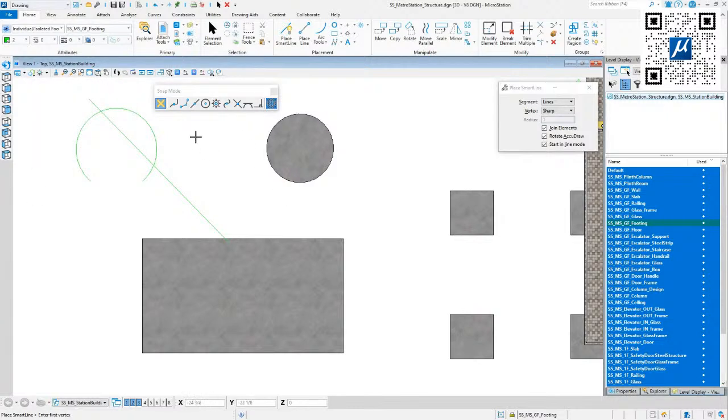And with this mode, I can go to key points. This is the center point. This would be a key point. There's an intersection. I don't have to change my snap mode that often. And now I've got everything I need, 99.9%. And sometimes I need a tangent or a perpendicular snap, maybe then I can change. So to snap to an existing element, that's very important to get an accurate drawing. You don't want to place the next element right next to an existing element. We want to go exactly where this intersection point is located. That's AccuSnap.